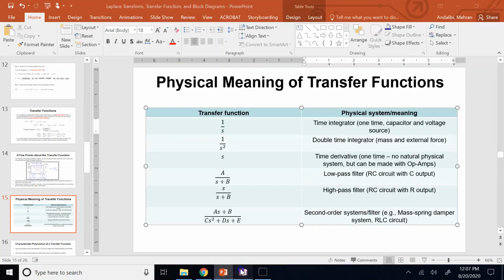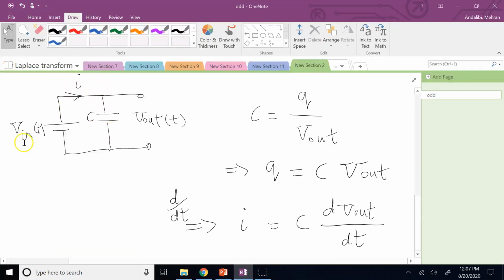One thing we need to change a little bit here, since I and V are related, but if V is constant, I is changing exponentially. So what I would like to do is, instead of calling it a voltage source, I would call it a current source. Okay, that makes life here, the modeling, easier. So let's instead use a current source. Right? That makes life easier for us. So this is I of t.